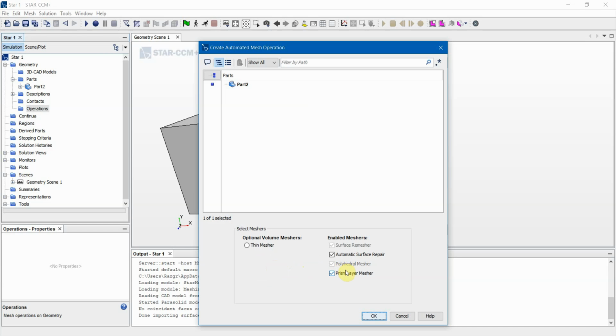So, again, I'll make a more detailed video about this when I have the time, because I want to actually plan this out. But the prism layer: every surface in air or water fluid has a boundary layer. If you're not familiar with that, I suggest you brush up on basic aerodynamics. But very quick overview with no pictures. Boundary layer is the layer of air, or fluid, that is forming on the surface where viscous effects cannot